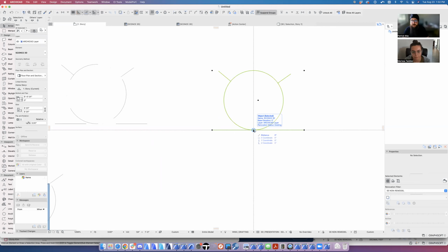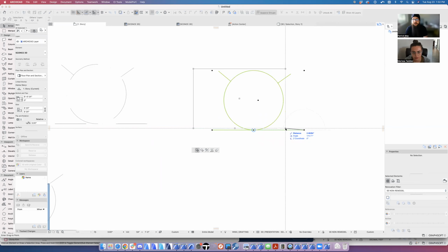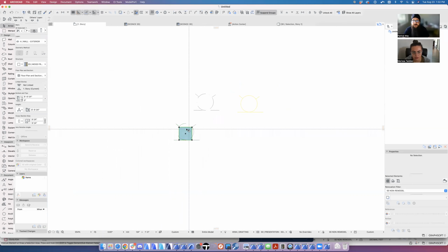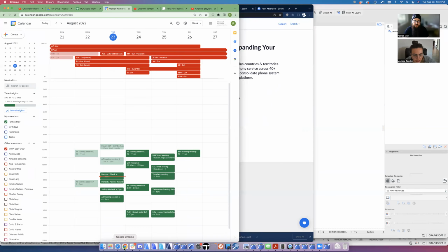Now, because we got rid of the mul command, you cannot resize or rescale this thing. So usually what I do is I put all of this stuff on a temp hide layer so that if I ever have to edit it, I can just change the 3D piece. As long as it's being saved from the same place relative to 0, 0, you can change the component, save it back out and copy and paste it into the object again. Okay, gotcha. There's a link I'll send you.